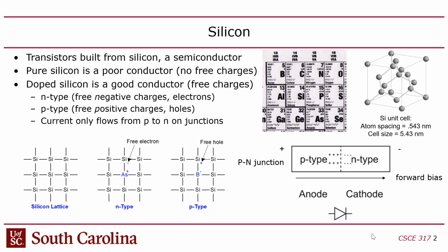And so if you have, for instance, a diode, where you have P-type, P-type is with the holes, so you add a dopant from group 3, column 3. N-type silicon is when you add a dopant from group 5, and silicon is in group 4. You end up with these charge carriers. If you have a positive voltage on the P side relative to the N side, that positive voltage will attract the negative charge carriers in the N silicon, and the negative voltage on the N side will attract the positive charge carriers, which pulls them to the junction. When they get attracted to the junction, they make this conduct from P to N. Likewise, if you try to send current the other way, it repulses them, and when you repulse the charge carriers from the junction, it cuts it off, so it won't carry current in the other direction.